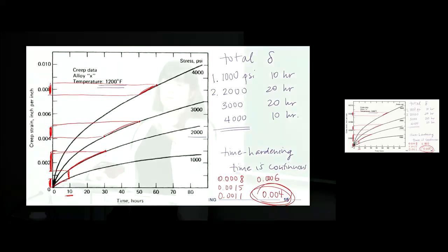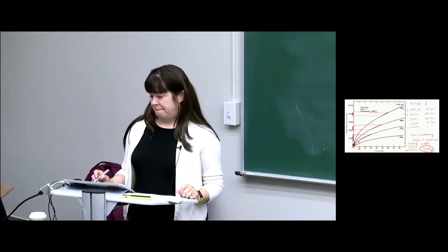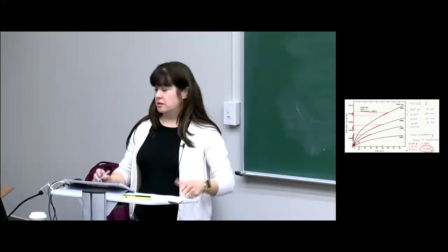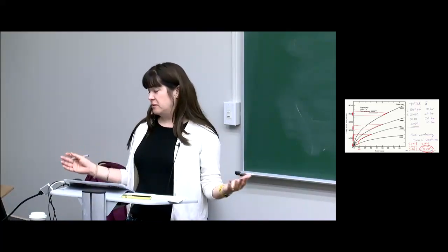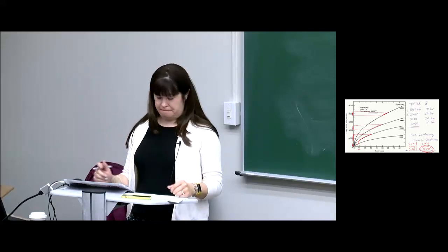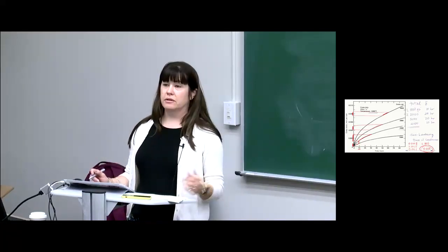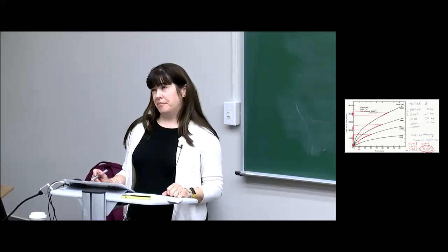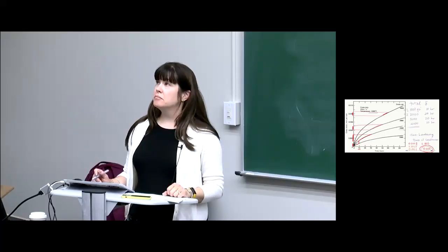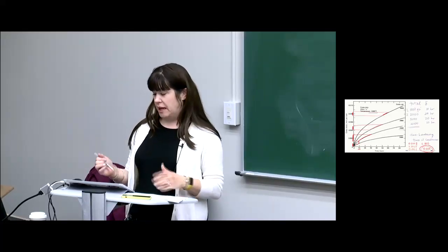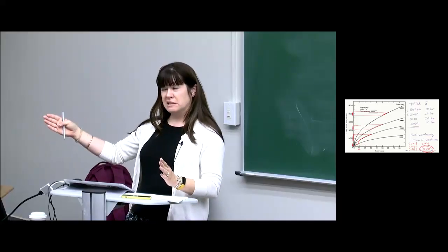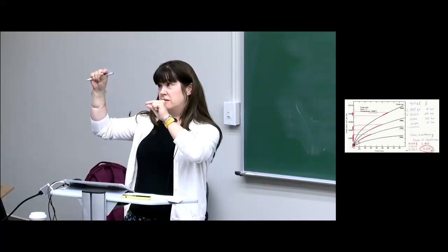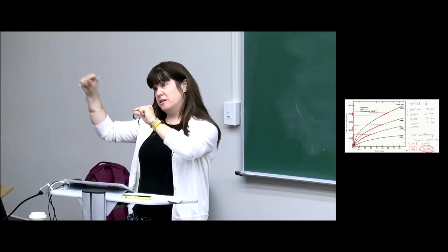All right, so one more question. That is for one cycle, yep. So now if the question asked you, we do this cycle 80 times, what's the total creep strain? Then you could calculate what it would be after that amount of cycles. So we could say that this represents that, but a more accurate way to do it would be to continue following out on this time path again and again, right? So the increments of strain are going to diminish the more we go along these cycles,